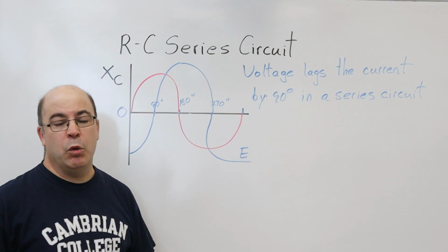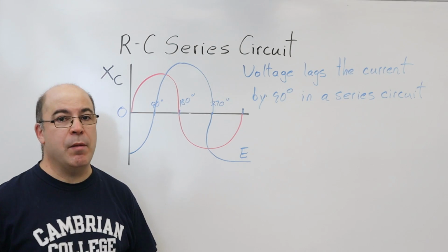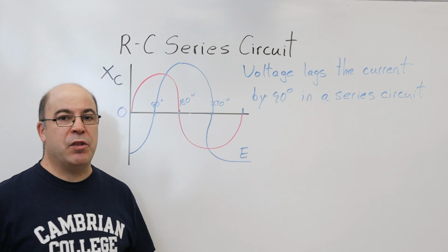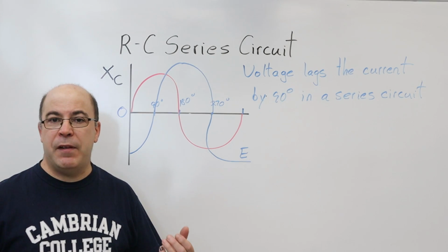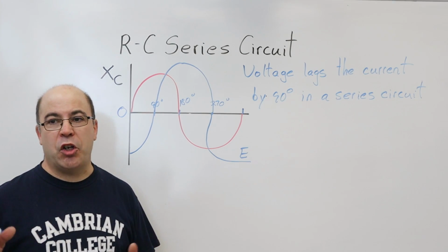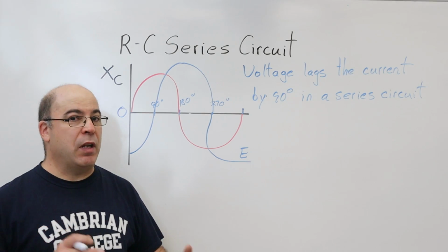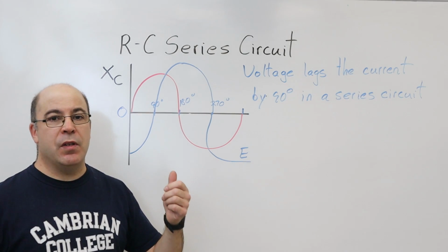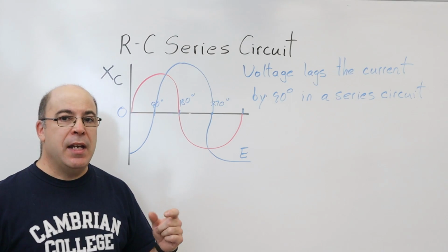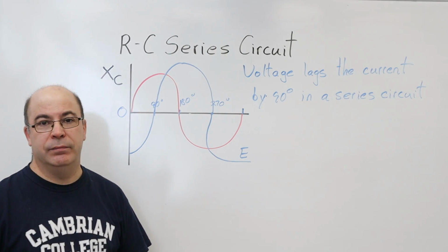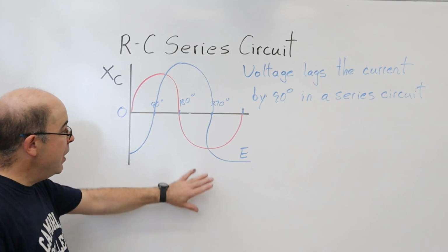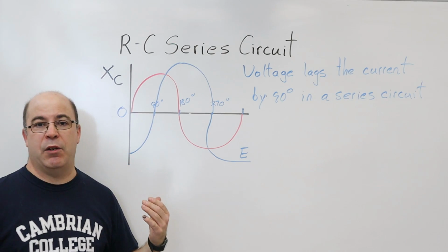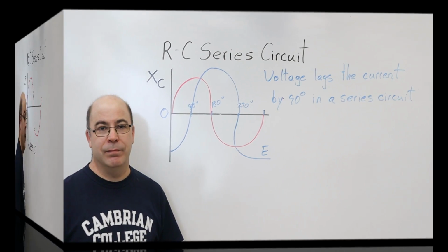Conversely, could voltage lag behind current in a parallel circuit? No, because the opposite is true: in a parallel circuit, the voltage waveform is fixed. It is stationary, and it is the current waveform that either leads or lags. So it's really important that we pay attention to the logic, the context, and that things are grammatically correct. Now, we've done this. I'm going to move on to drawing this out for the entire circuit. So I'll be right back.